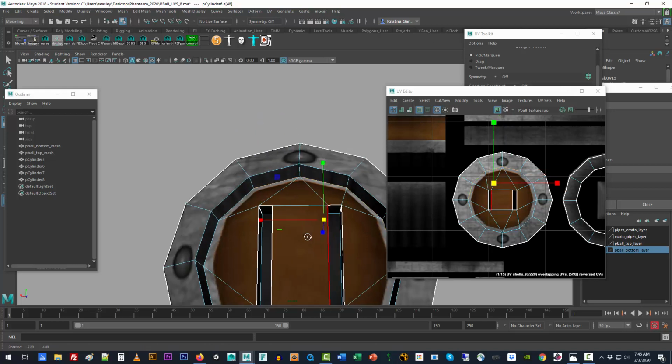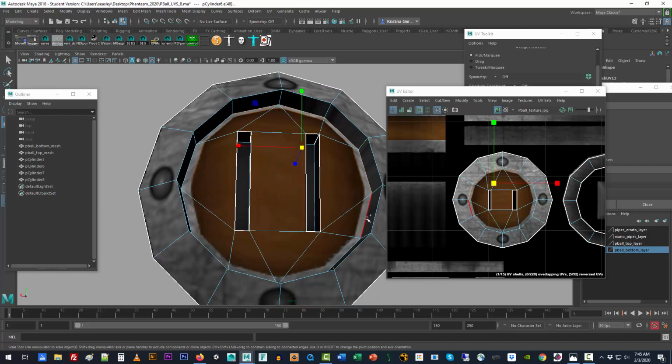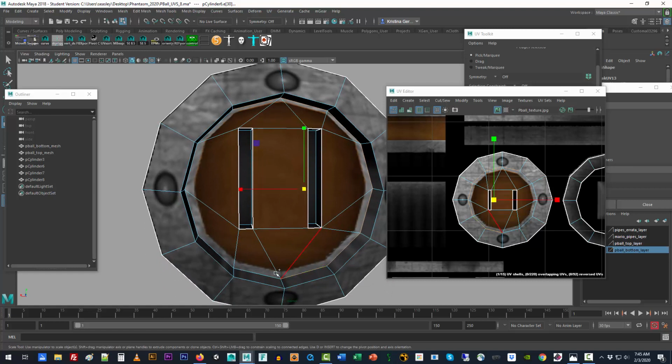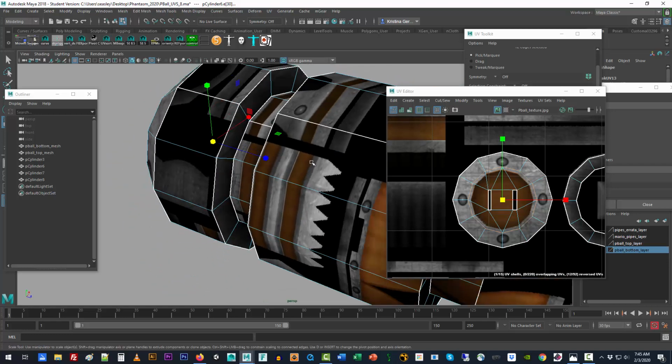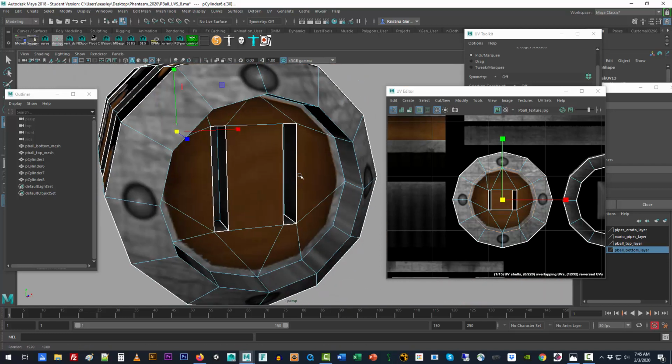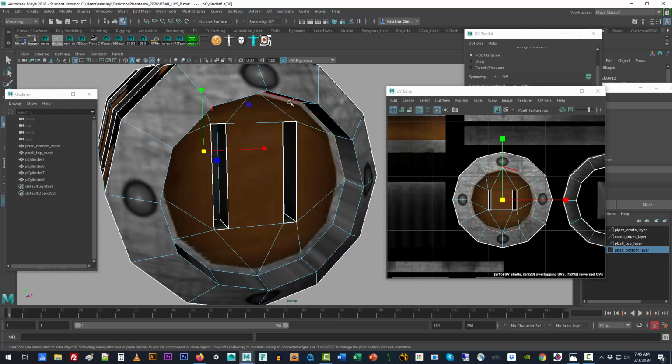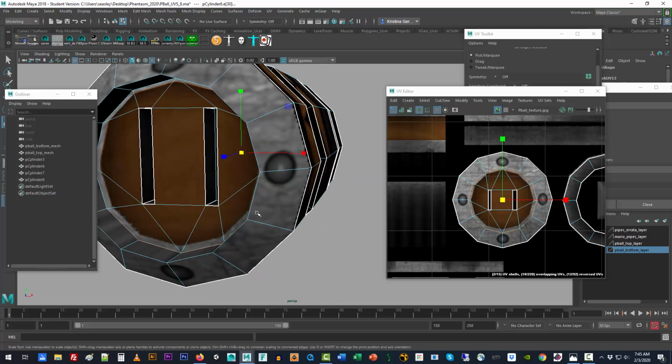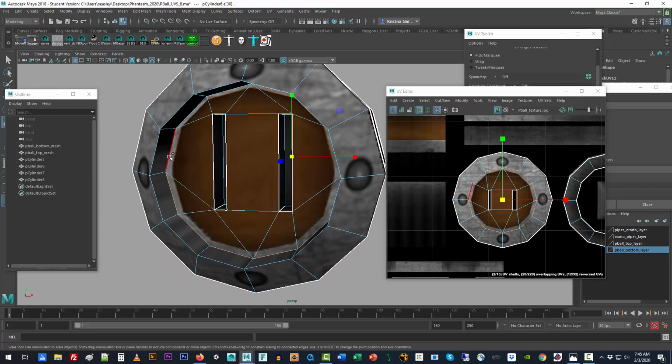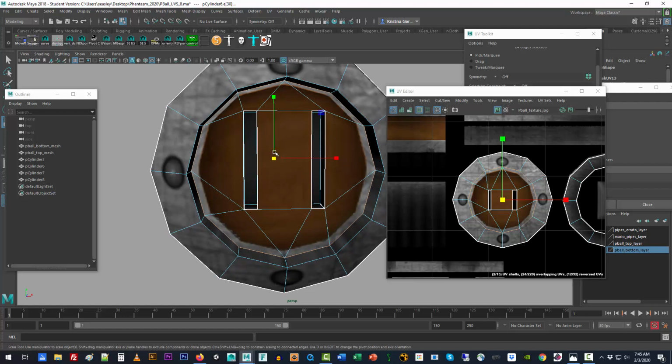I'm just going to choose the most accessible way, which is that I'm just going to go around, since the double click trick doesn't work if Maya gets confused about where things are. It just means I have to spend a moment selecting that edge, going around to the back and selecting the same edge, and then once I have them both chosen, I'm going to scale them down a bit in the UV editor, because that's what's going to separate them from the edge that's in front and keep it from being this kind of line.